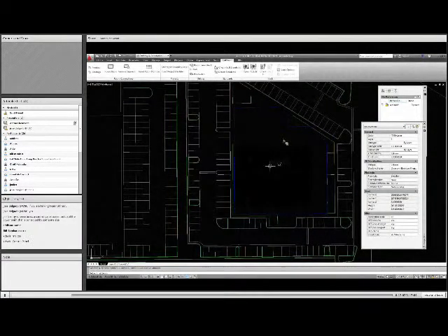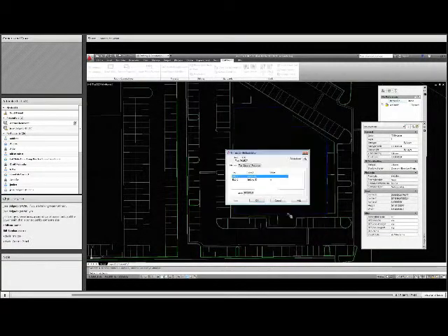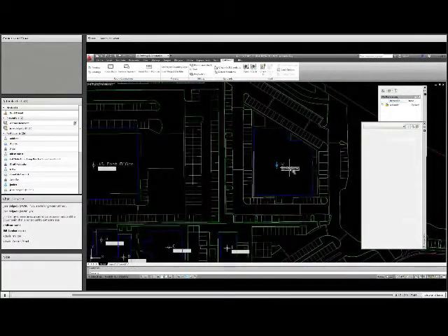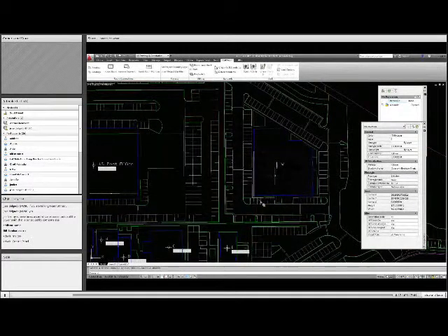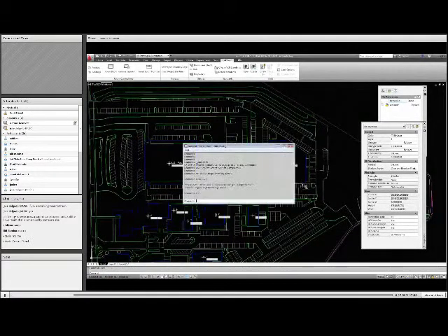So now that I have those, I don't have ArcGIS for AutoCAD running, so I'll get that started up. And if I look at my feature classes, oh, I don't actually have any. So I have another custom command. It'll go through, read the Excel file, and create the feature classes, transferring the data where appropriate. So like the buildings will actually transfer the building ID. So you can see down here in the properties, we have building W.